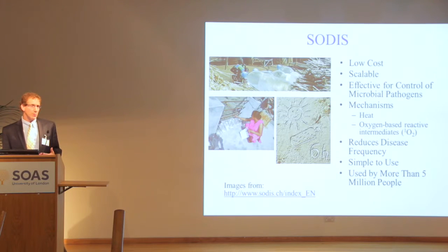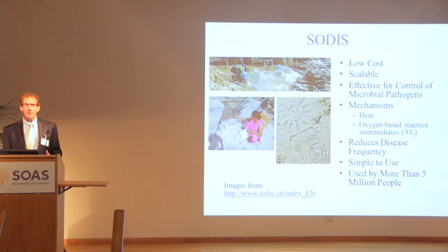And that was part of the motivation for development of SODIS, which probably most people in this room are familiar with. This is a technology that's low cost and scalable. It's very effective for control of microbial pathogens. The mechanisms of microbial inactivation are reasonably well known to involve both heat and in some cases some oxygen-based reactive intermediates, including singlet oxygen. And disciplined application of this process has been demonstrated to be effective for reducing disease transmission, which is the ultimate goal.